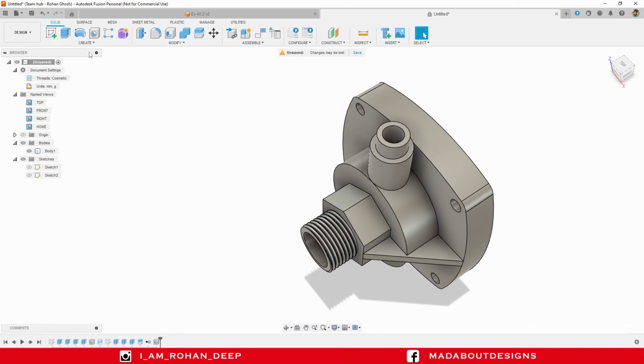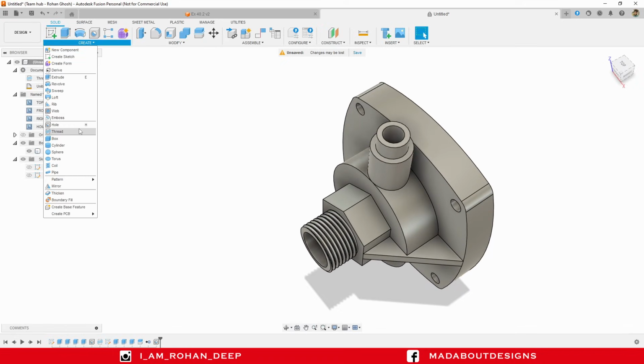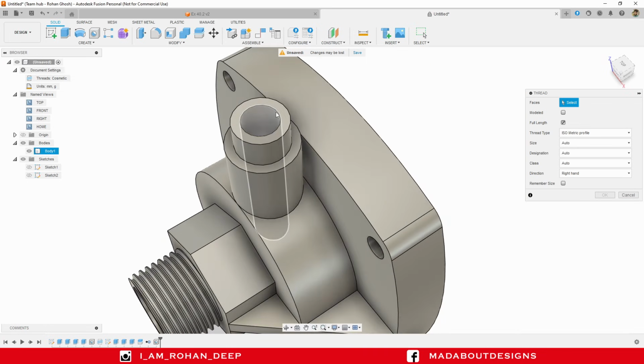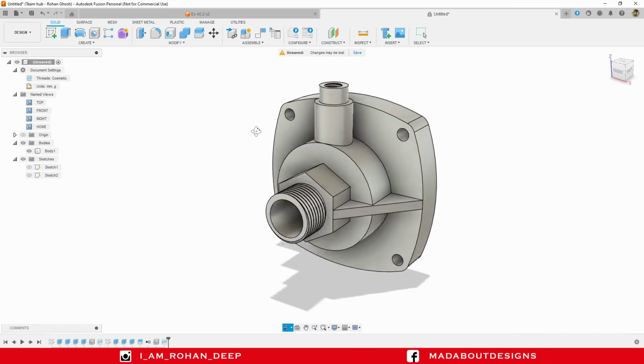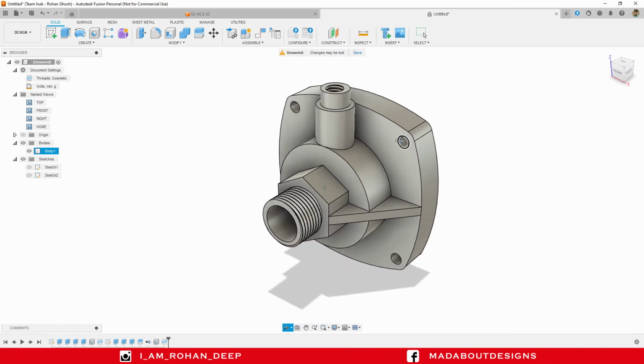Now go to Thread again. Select this inner profile. Change the pitch. Here I will choose the pitch as 1 mm. Turn on this model feature and direction right-handed. Click OK. Here is our body almost ready.